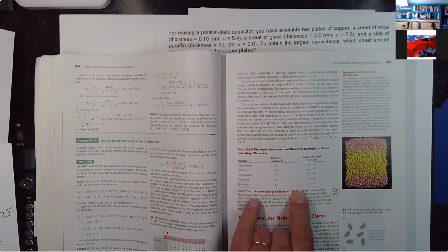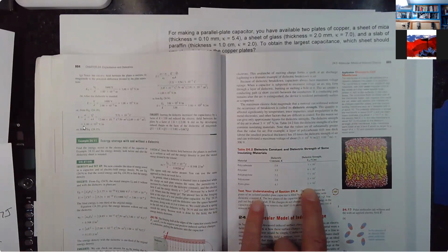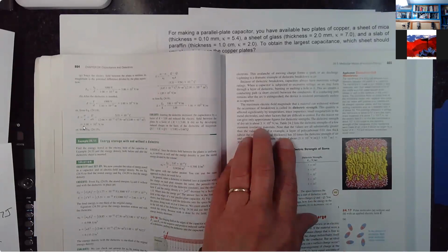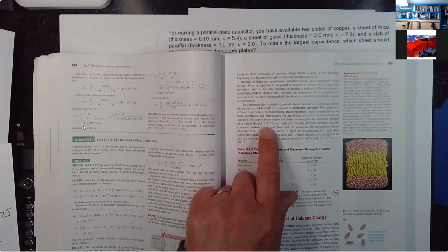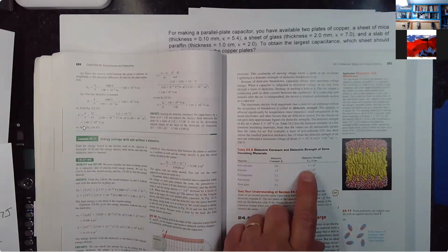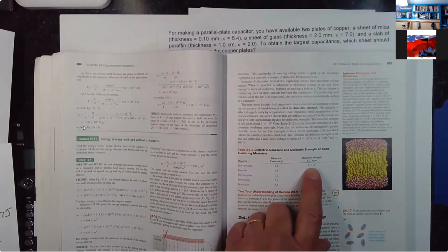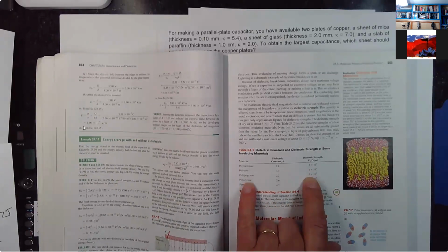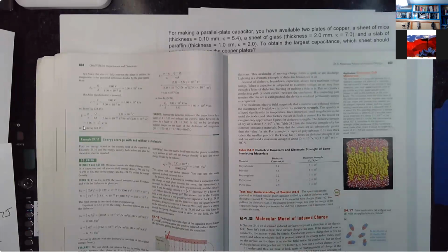They've only got it for a few, I guess. But they don't have air. Well, maybe they mentioned that. Yeah, the dielectric strength of dry air is 3 million volts per meter. And for these other things, this is like 30 million volts for polycarbonate, 60 million for polyester, 70 million for polypropylene. Polystyrene is 20 million, and Pyrex glass is about 10 million.